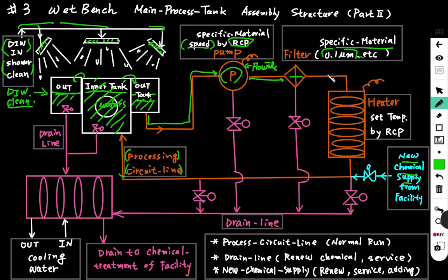And through the filter, the solution goes to the heater. The heater set point can be set by recipe. And the heater heats the chemical. Then the filtered and heated solution goes back to the inner tank.